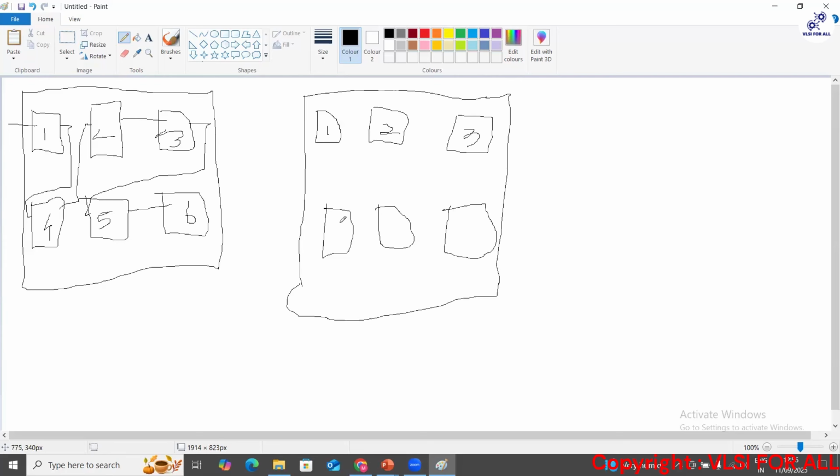On this functional mode, when I checked it, I understood that my design works very properly when I have the flop placement in the same manner. So I don't want to alter this flop, because maybe this flop communicates with some ports or some logic sitting over here. So now in the scan chain ordering, I just want to check whether these flops are working fine or not.